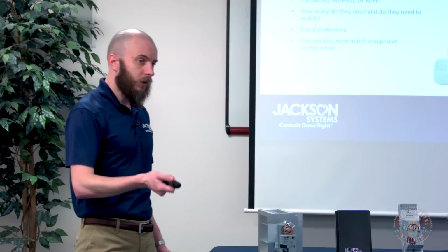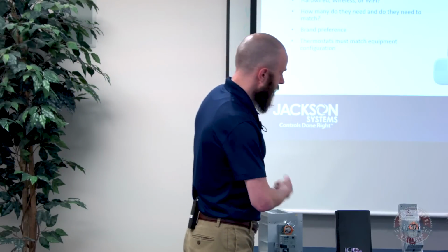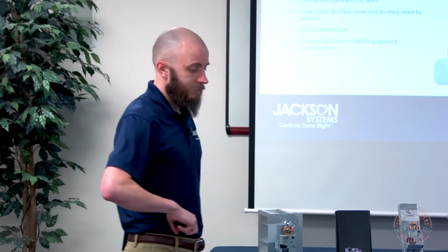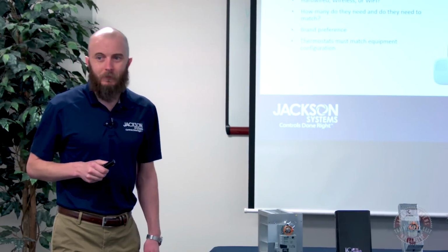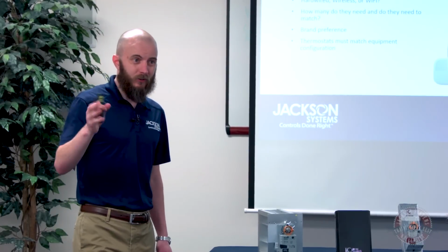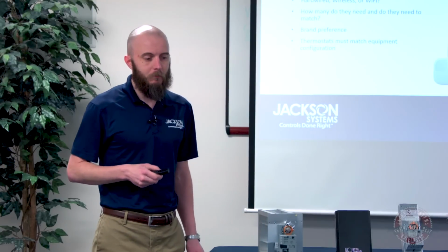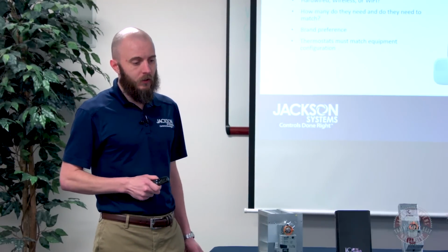In most cases, you will need a common wire. I know the IO zone panels do not play very nicely with power stealing thermostats. So any thermostats that are going to give you a little bit of a non-standard signal back, whether it's power stealing, you might only get 18 volts back or something like that, not every zone panel is going to read that properly. So we recommend staying away from that. But for the most part, most thermostats are going to work.